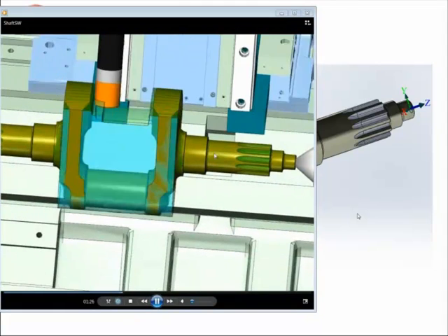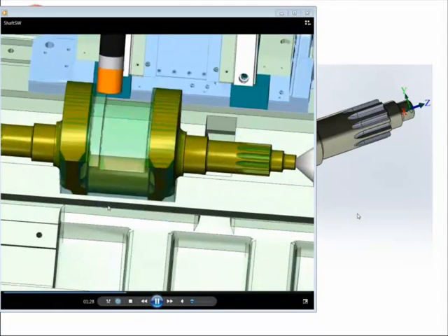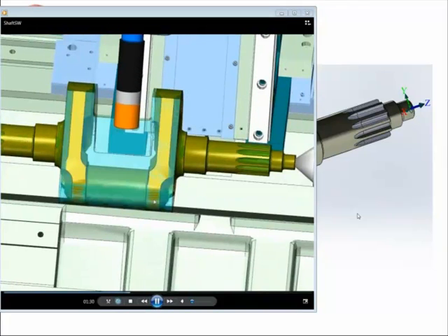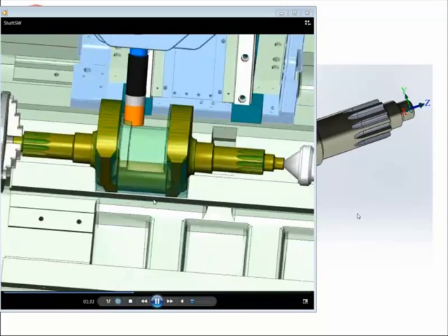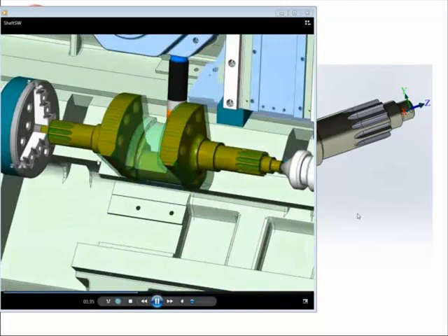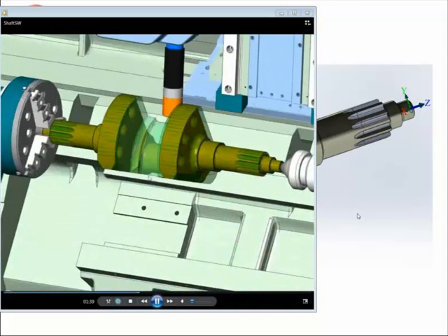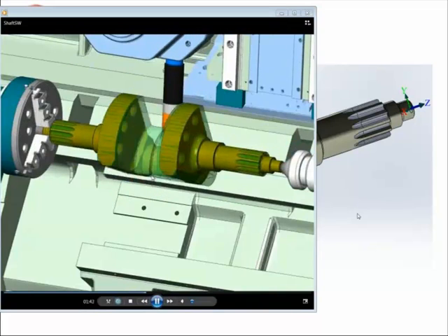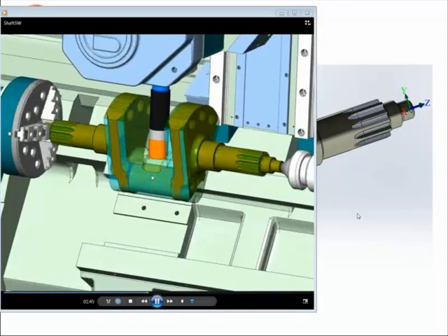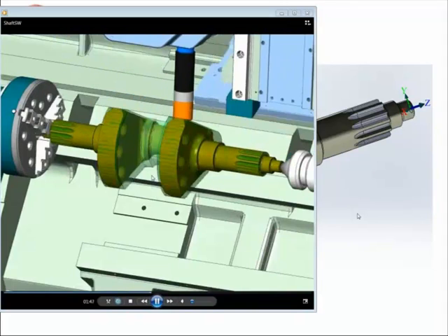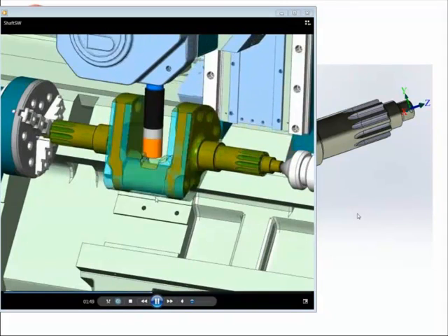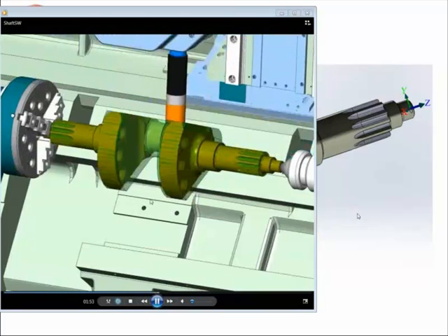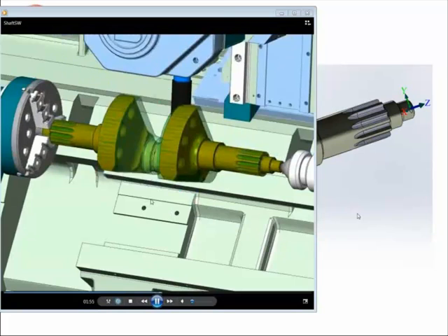And it's trimmed. The actual toolpath goes right around the cylinder, but I'm using stock recognition, so Mastercam knows what the stock is, and it won't rotate all around that eccentric cylinder when there is no material. It only rotates as much as it has to out here, but once you get closer to the cylinder, there will be material left. So then it will start rotating around right here to give you that tolerance.